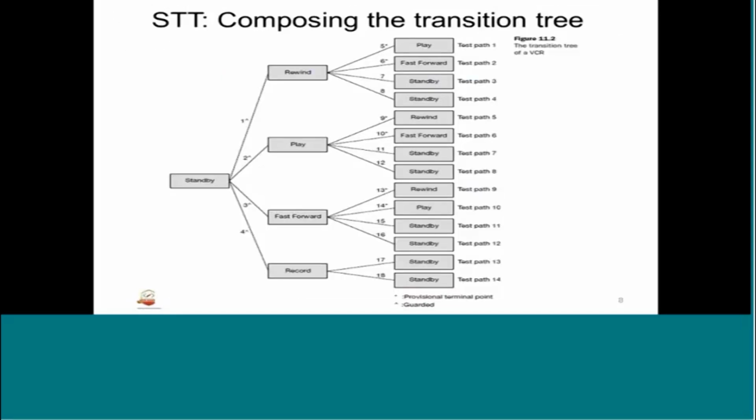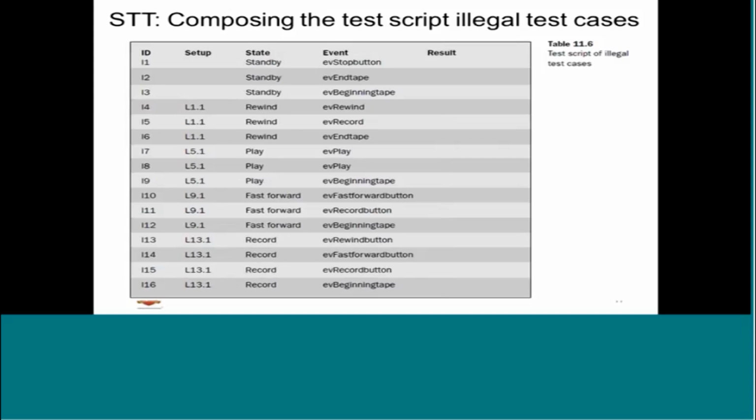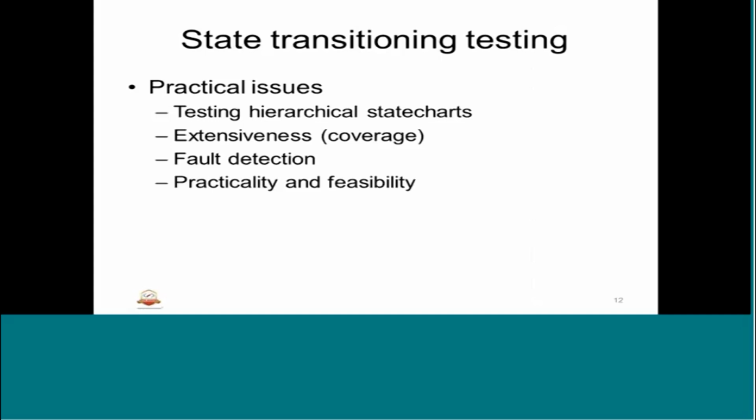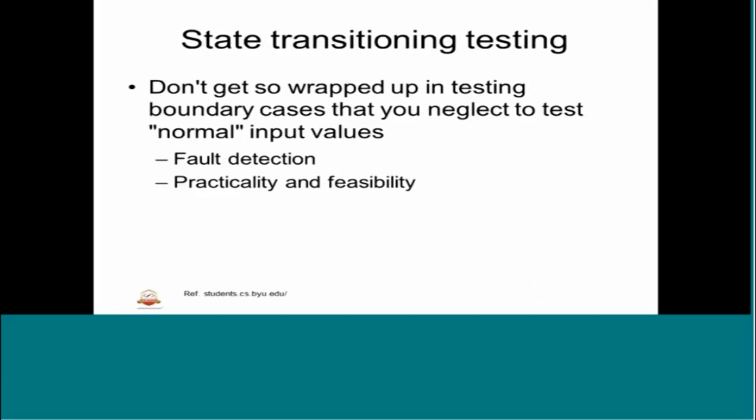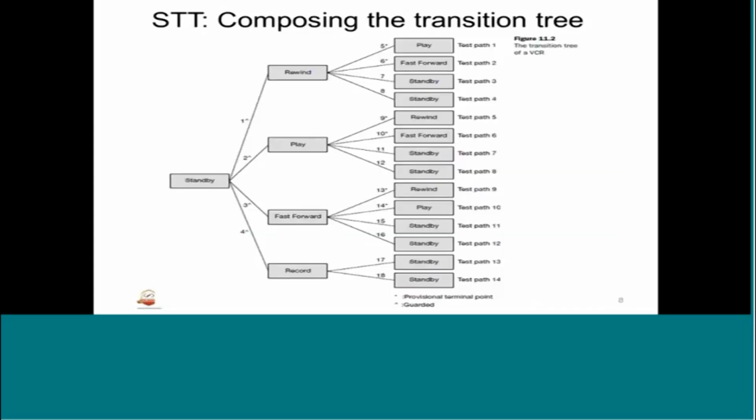It's very important to have state transition testing because embedded systems mostly live with state transitions, but there are practical challenges and issues in doing that state based testing. We need to overcome them with the help of all these mechanisms and the best expertise we can have in terms of system knowledge and the states that we can enter. Okay, that is about state transition testing.